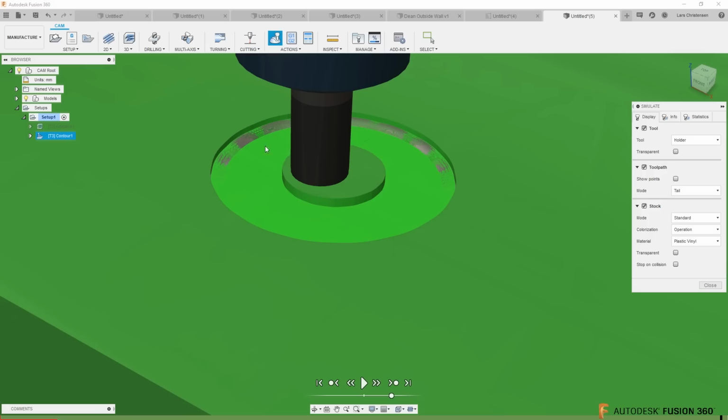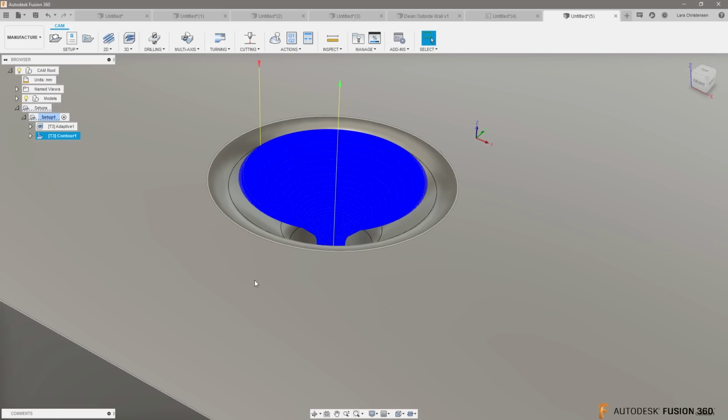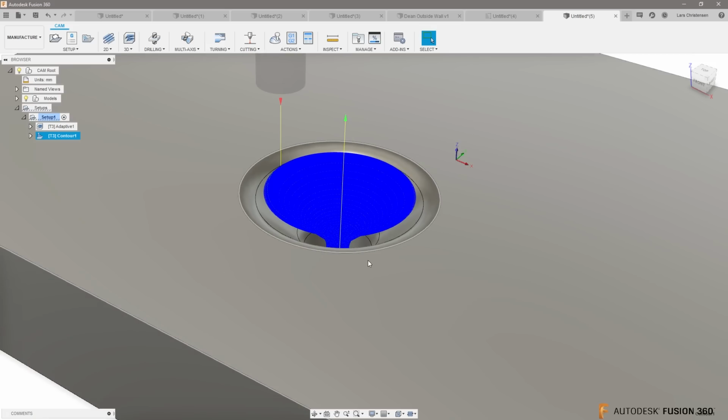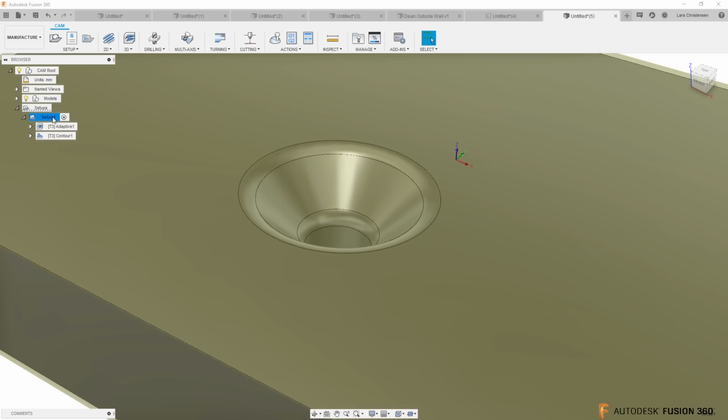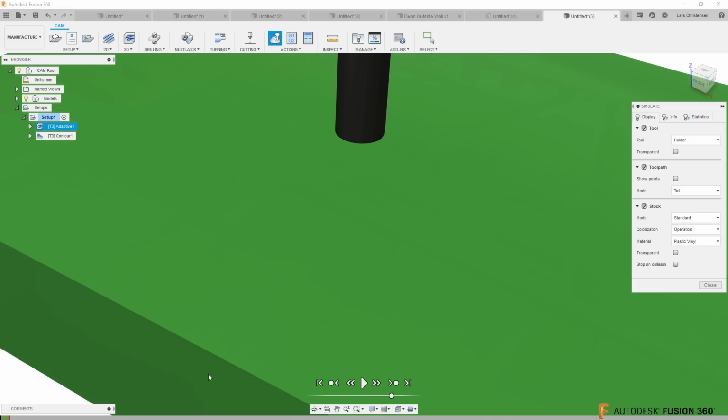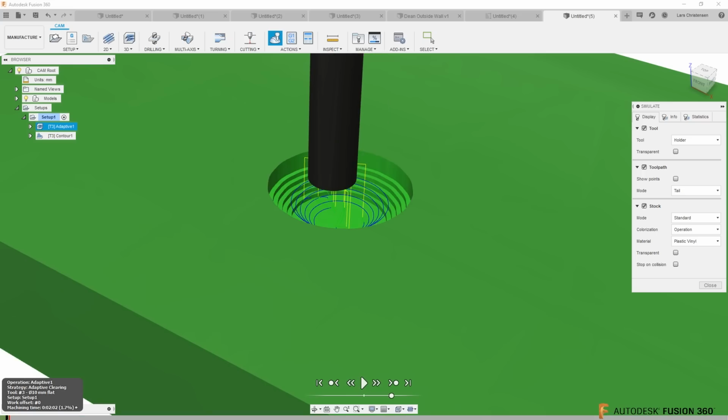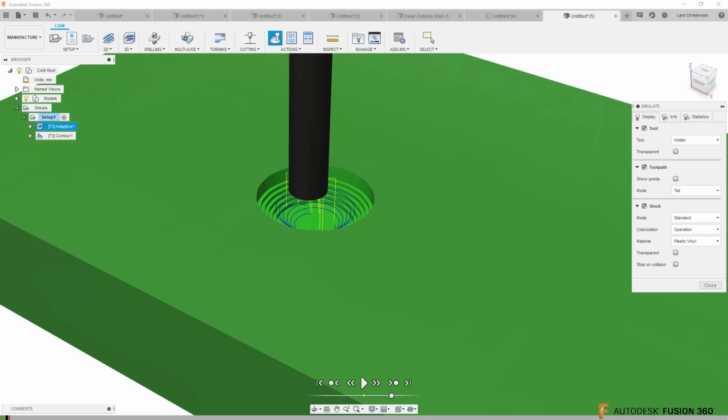with something that will resemble, I have a little bit of extra stock on top, that's why you're going to see a little bit of step here, but you will end up with something that resembles the radiuses on it. If you're using a ball end mill, then you will actually end up with something that looks a little bit more right. Let's see here. All right. Okay. So that is that. Hope that's helpful. Moving on.